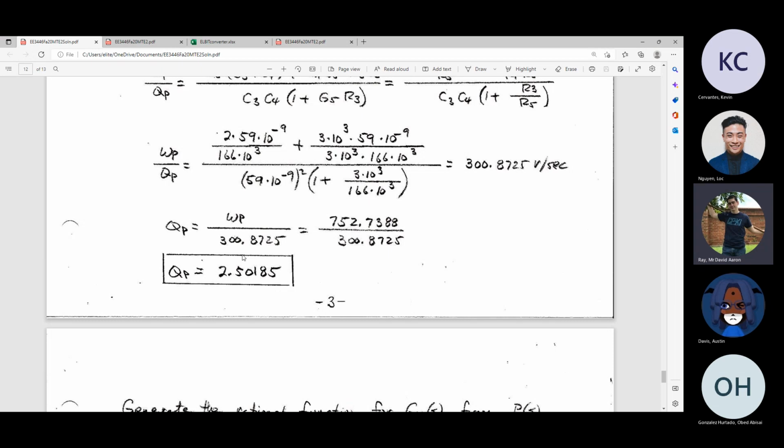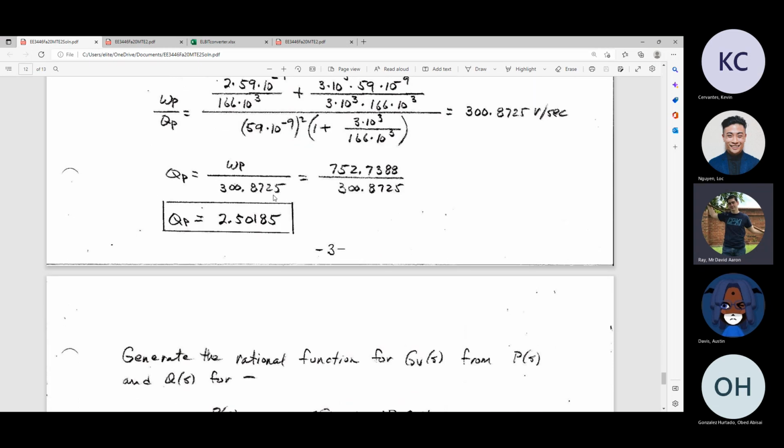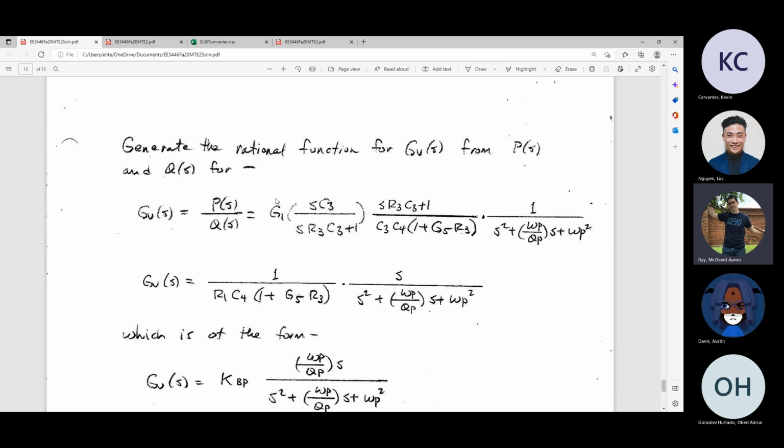But if you have a really, really high quality factor, then the response is going to be really slow. It's going to slowly rise up. It's going to take a few seconds to get to the 48 volts, but the final 48 volts is going to be much more straight. It's going to be a lot less sinusoidal. And so the question is, how do I balance the two? How do I make sure the response is quick enough that nothing blows up, but also not so sinusoidal that it also blows up? So take whichever blow up you want. There's a whole bunch of design specifications I have to figure out for that.